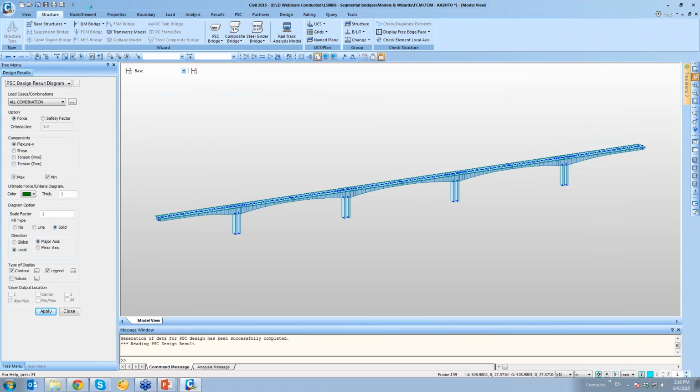Once it is done, we'll give the section a bit more height, so the M by Z component would be reducing. So P by A minus M by Z would obviously be under compression rather than under tension. And we'll also reduce the number of pairs. With 4 pairs, the time in generating the model is increasing.